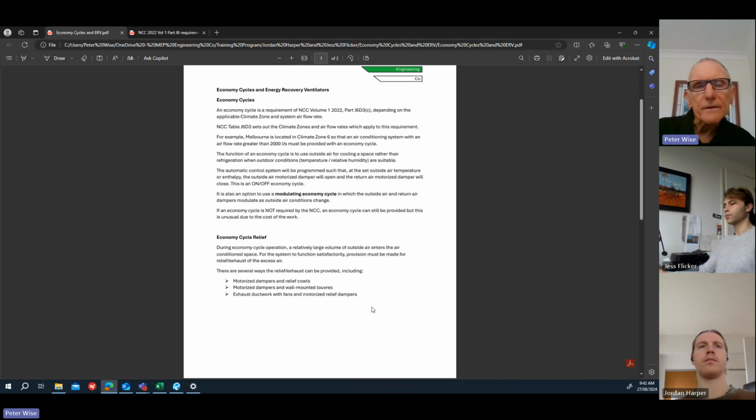Right. Yeah. I mean, if you work out that the pressure that you develop by the economy cycle is enough to push the air out through ductwork without a fan, don't put one in. But don't overlook that possibility. But relief is extremely important, because if you don't have relief, it's not going to work properly, which is the same in all these situations of balancing.